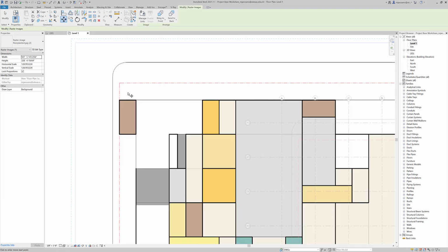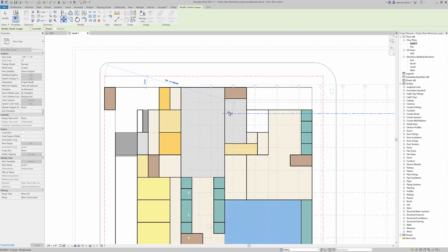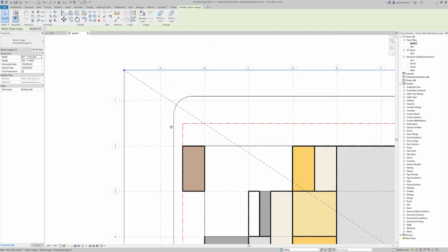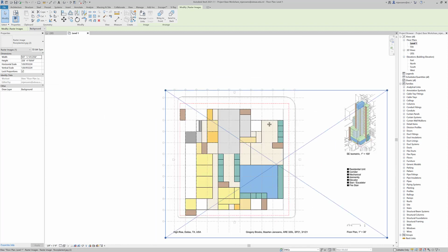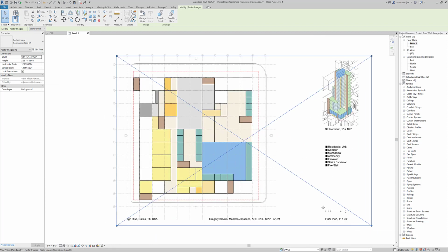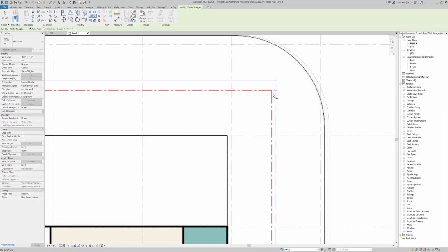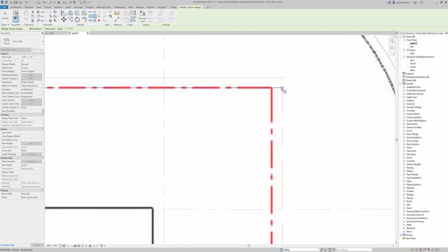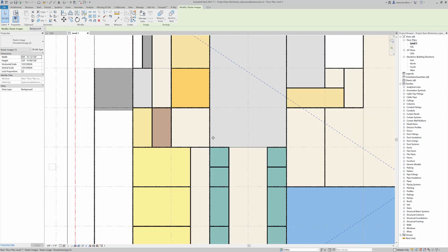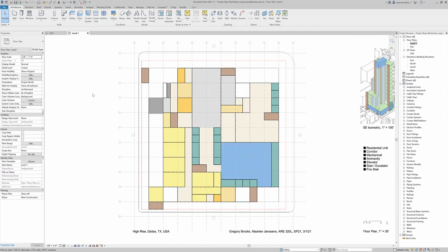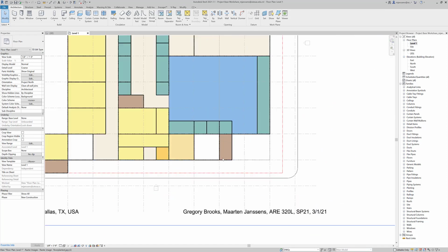And then I just need to move this from this point to where it needs to be on the site. So that should snap into place. And it's not 100% perfect. You can see that it's maybe a little bit off. So you could rescale it to the site. Actually, a bigger dimension might help you here. So we're going to scale it from this to this, and then that will give you all of your lines that you need for your rooms, for instance. So that's the first method. It's not super complicated, and it doesn't really get to any sort of parametric or snappability.